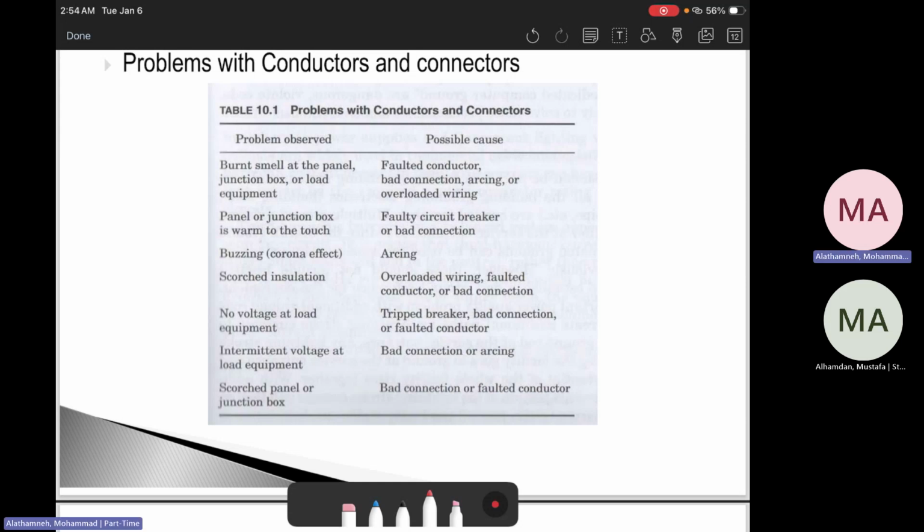I once saw a whole building complaining about bad electricity. The utility was fine. The real issue was that the neutral bar screw was loose. So under a specific load, the neutral floated and the voltage jumped between the circuits. Fixing one screw solved the entire building. So if there's a loose neutral or a loose phase, it can create a big problem, which is something we don't want.